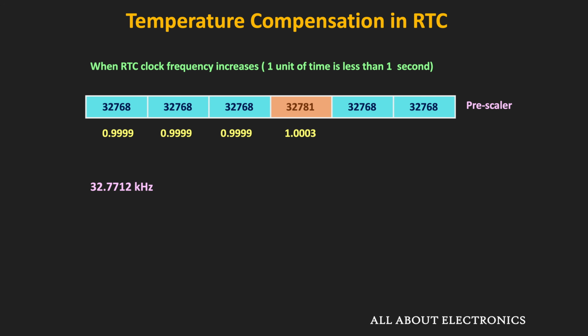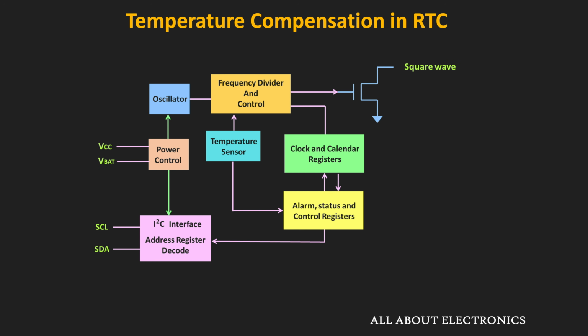Apart from that, sometimes, to make the RTCs even more robust, temperature compensated crystal oscillators are used. So these are some of the temperature compensation techniques used in current RTCs. Apart from that, some current RTCs also consist of a watchdog timer and tamper detection circuits. Using the watchdog timer, if the controller or the processor is stuck somewhere during the execution, it is possible to reset it.